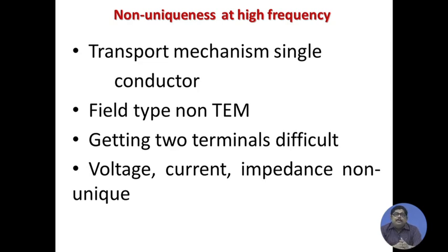But one problem at high frequency is that the transport mechanism, through which power gets transferred, is generally in the form of waveguides, which are single conductor, not two conductor, because two conductors become lossy at higher microwave frequencies.